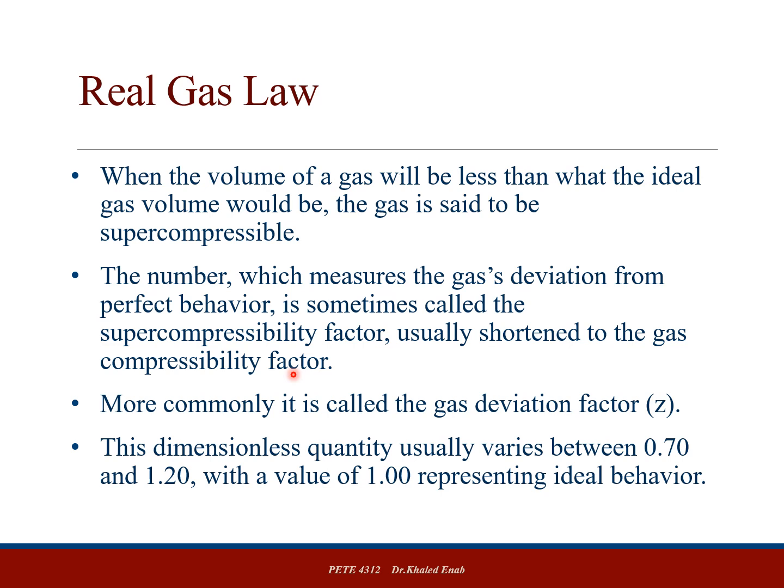Isothermal compressibility is used to calculate the change in volume. The gas compressibility factor, or simply supercompressibility factor, is used to define the deviation of the gas behavior from ideal behavior, so how much this gas deviates from ideal behavior according to pressure, volume, and temperature.